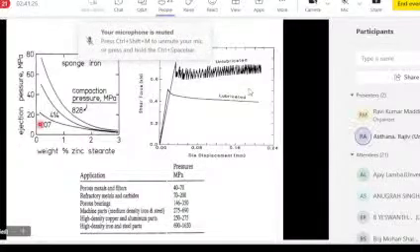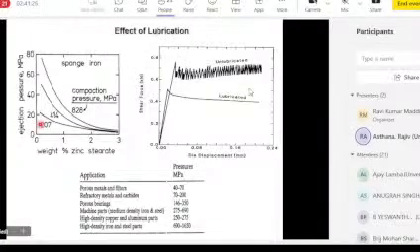These are standard pressures used in industry for different materials, and you can see they are typically in a few 10 to a few hundred megapascal range. For very, very high density parts, you may have to go to gigapascal range, almost 1,000 MPa.